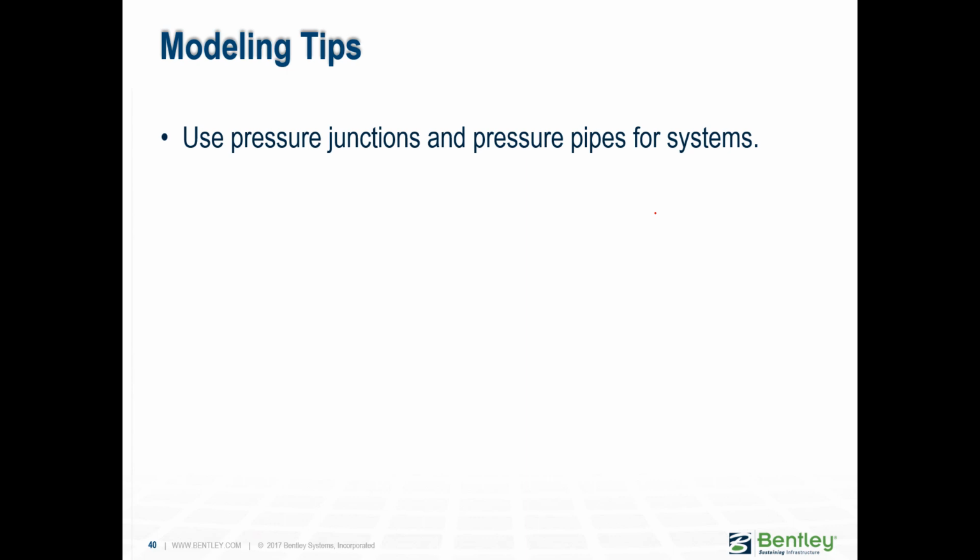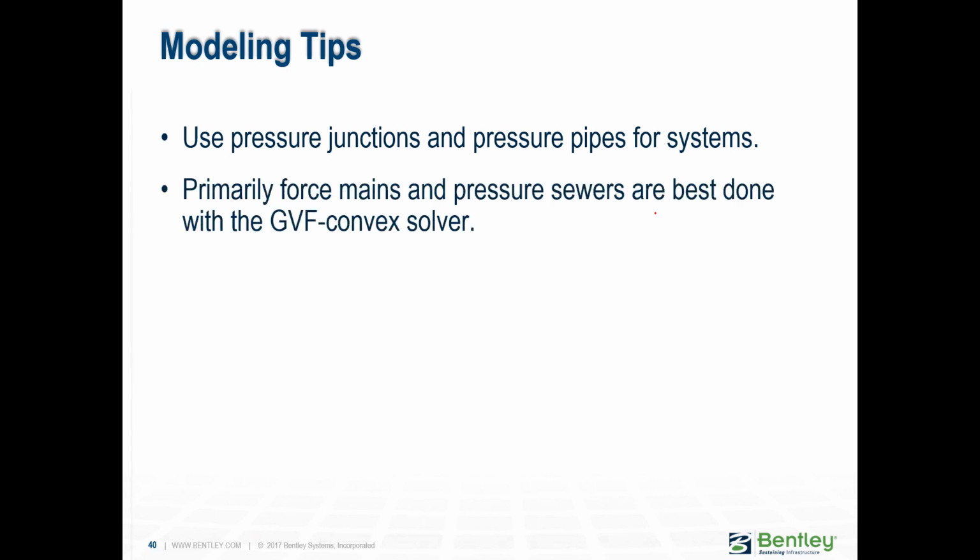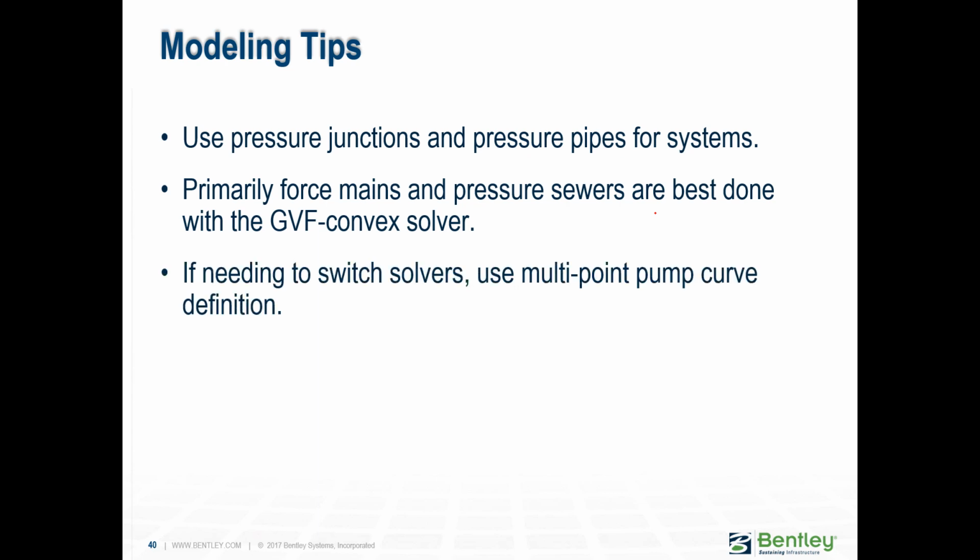Okay, so to finalize this pressure presentation, remember to always use pressure junctions and pressure pipes when you're doing a pressure system, because sometimes people forget and you put a gravity pipe and then you can't really connect it to a pressure junction and things like that. Again, we always recommend that you use the GVF-Convex solver for pressure sewers and anything pressure.